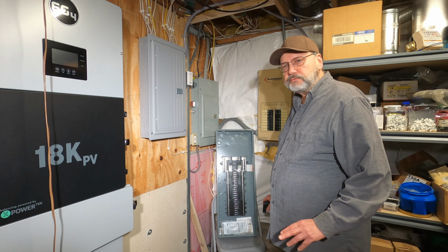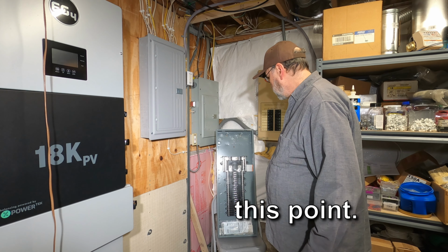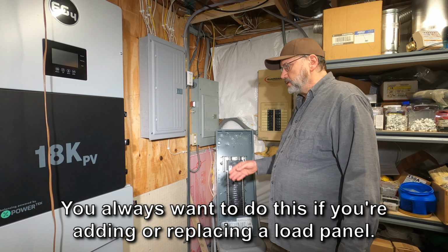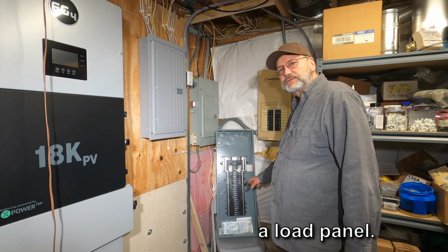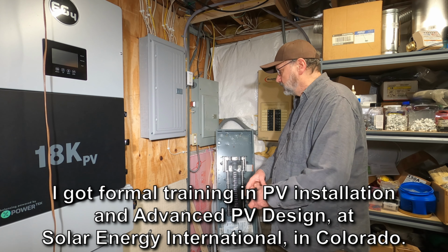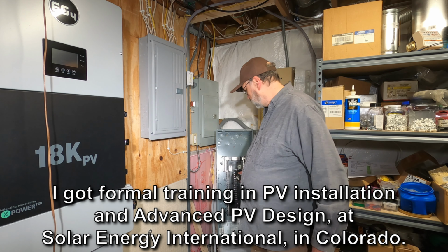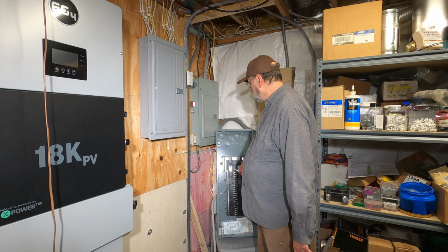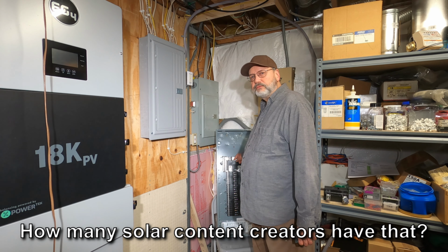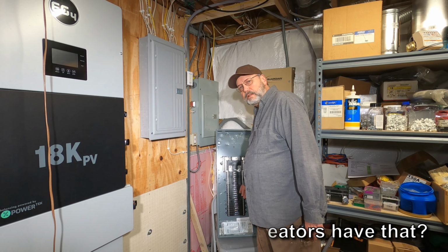So a major goal of doing this service load calculation exercise is that when you're installing solar and you're backfeeding it onto the load side of the main breaker, you need to know that the power that you're backfeeding through a circuit breaker into the bus bar, plus the power coming in from the service, can't overload the bus bar.